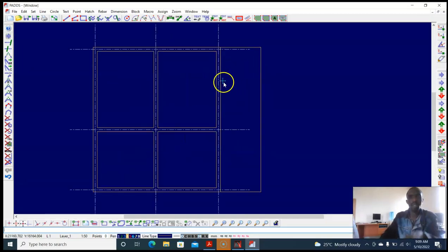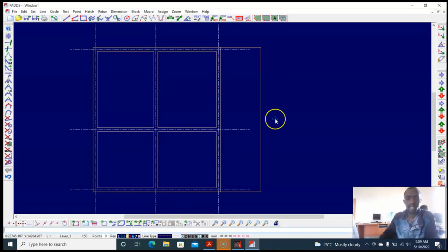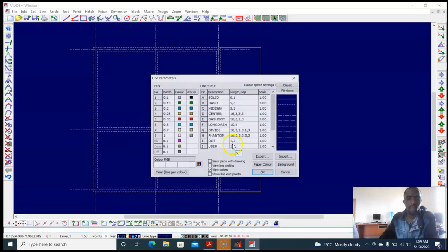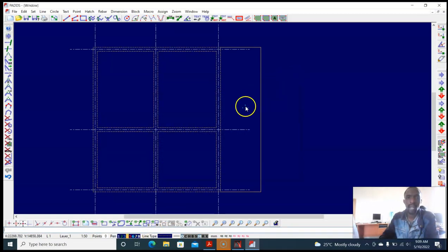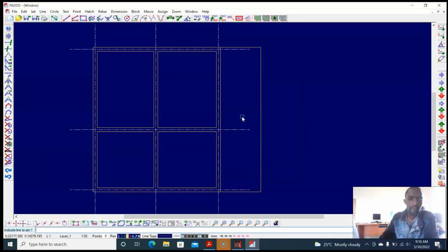So if this is the cantilever, let's do these beams dotted, hidden lines, to show how to properly detail them. So I did LG, I came here, chose hidden, then LS, then I applied. Let me do that again. I came here, chose a hidden line, and then typed L, S. Then you click, click, click, click to apply properties.